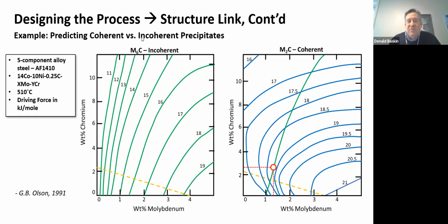Of course, I should mention this. The density obviously doesn't stay constant, right? Because as you add chromium and molybdenum, you're going to increase the density because those elements have a higher density than steel. So there's probably an optimization problem here. Where do you start increasing the density? Where do you maximize the strength? What's the density at that strength? But if you weren't so worried about that, this right here is what would give you the strongest material.